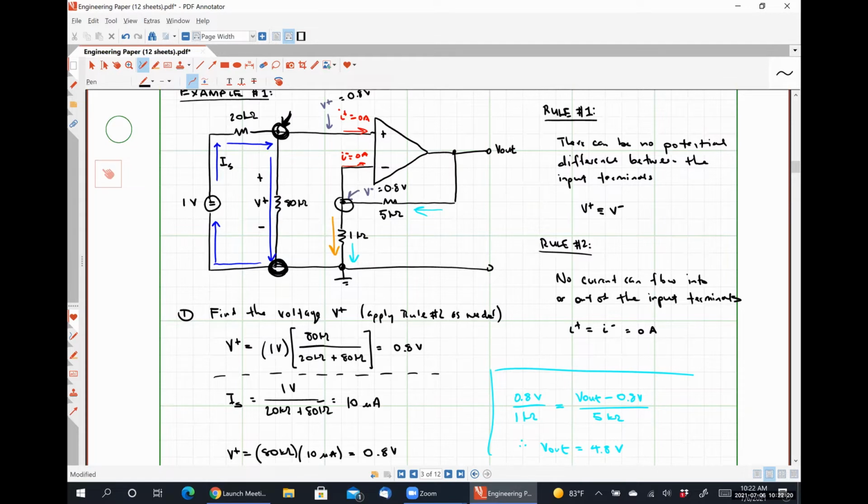Okay, I got it now. Yeah. The voltage present at the inverting input terminal is the exact same thing as the voltage drop over the 1 kilo ohm resistor. But we always find the voltage at the non-inverting input terminal first, and then use that to solve for V out. If we didn't figure out what the voltage at the non-inverting input terminal was first, we actually couldn't solve for V out, because V out is always going to wind up in an equation with V minus.